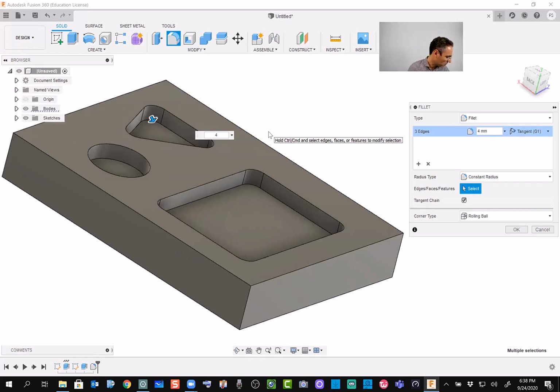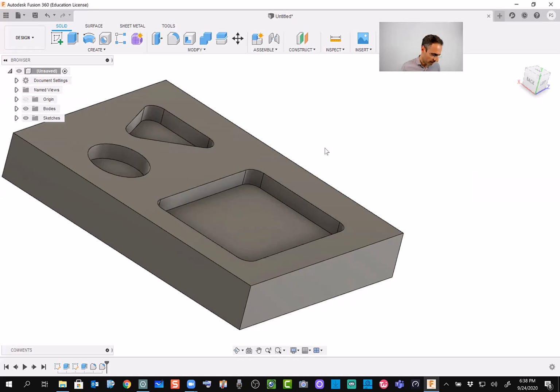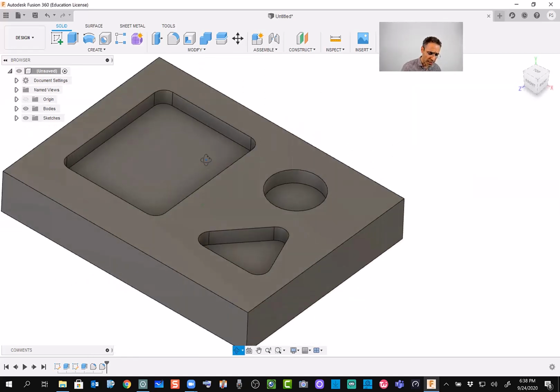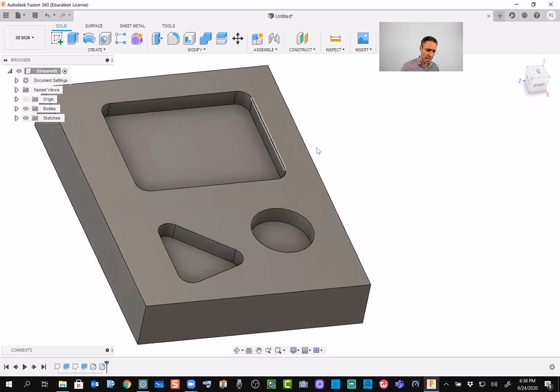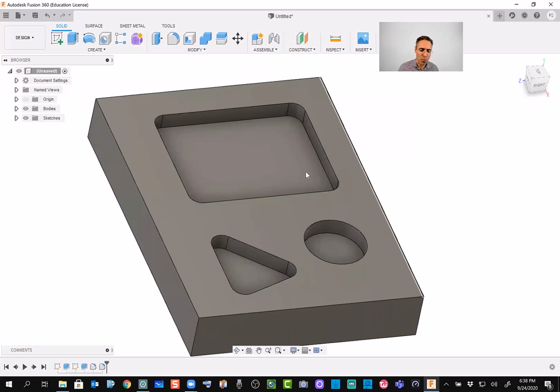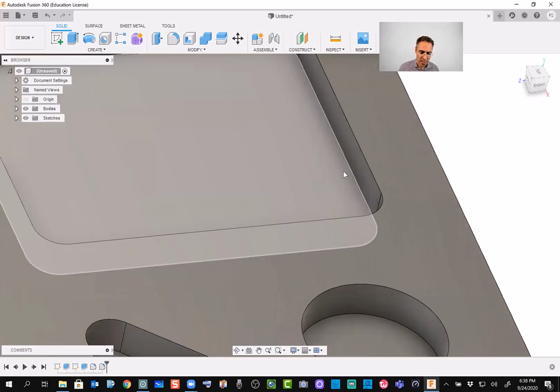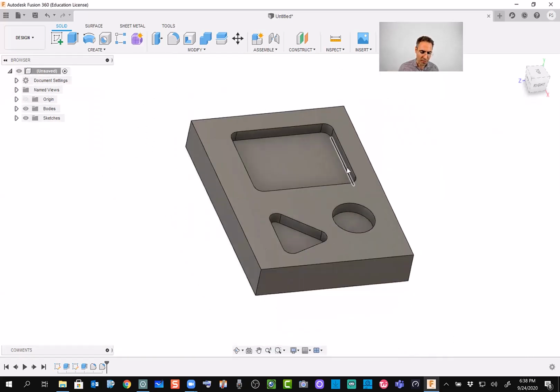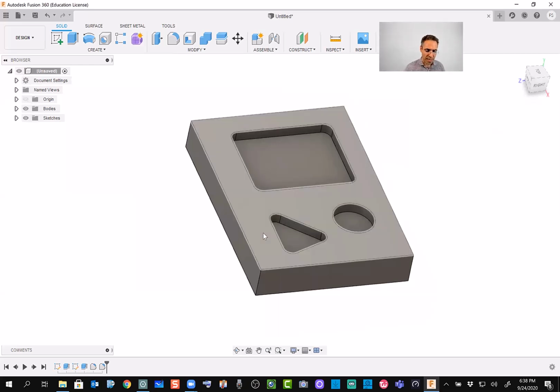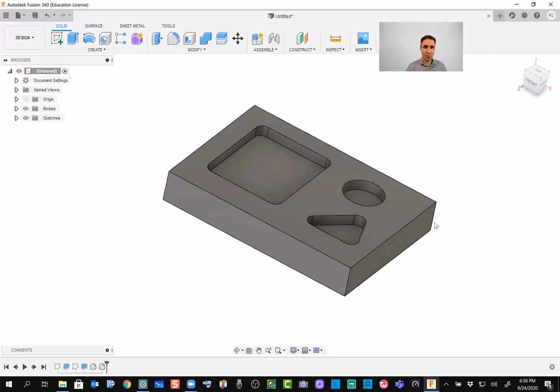So, 4 for this one, all right? So, we create the pocket that we want. It's smooth, it's okay. You can even change the radius for here, but that's fine. You will see we have tools to create this sharp corner at the bottom, right? Problem is this round corner around here. So this is the pocket that we have, and this is a part that we are happy to make.